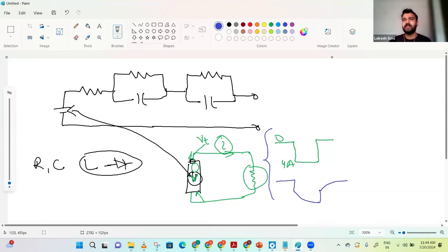Now, it can be an RC circuit or some other element which is also mimicking this, and we can use that also. But what we realize is current can be drawn immediately, so inductance is not required, because inductance should be used when there is inertia in current flow. But in this case, we see inertia in voltage. Voltage doesn't drop immediately. There is this dynamics, which we see as time constant dynamics. And to mimic this voltage dynamics, the RC combination is the right combination in an electrical circuit.